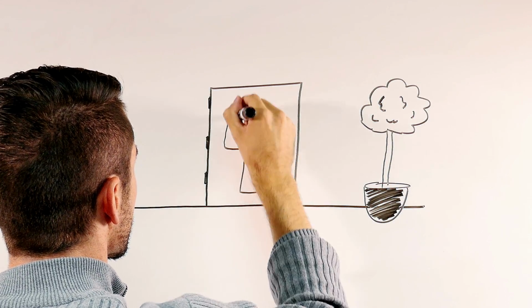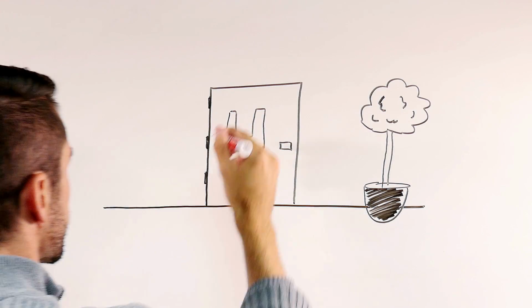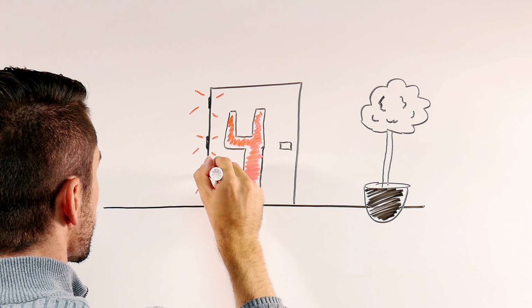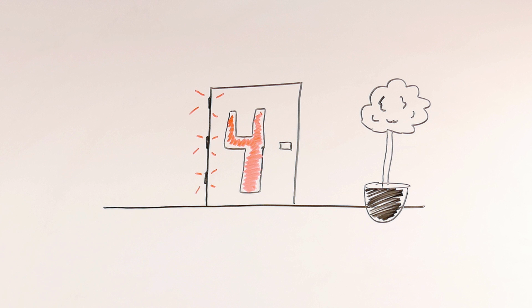A full mortise hinge means one leaf is mortised or set into the edge of the door, and the other leaf is mortised into the frame. On full mortise hinges, only the barrel can be seen when the door is closed. Full mortise hinges are the most common type. Ives designates full mortise hinges as type 1.